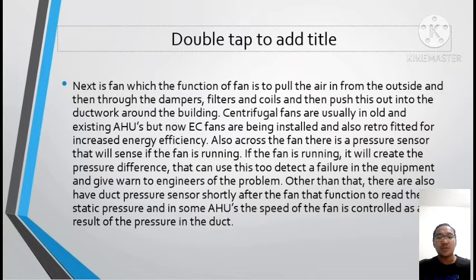Other than that, they also have a duct pressure sensor shortly after the fan that functions to read the static pressure, and in some AHUs, the speed of the fan is controlled as a result of the pressure in the duct.